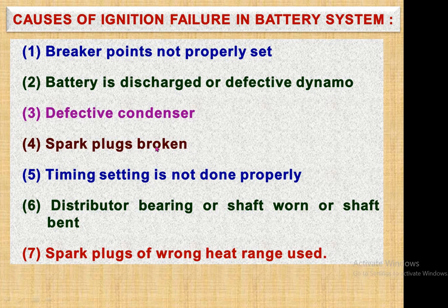If the spark plug is broken, the tips of the spark plug are broken, then there will be no charge carried from the top to the inside of the cylinder. Timing setup is not done properly. The timing of the charge that has to be delivered at the proper time after the end of the compression stroke, when it should be delivered, should be set properly.